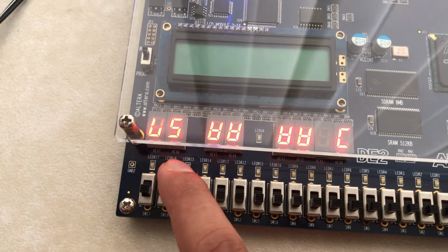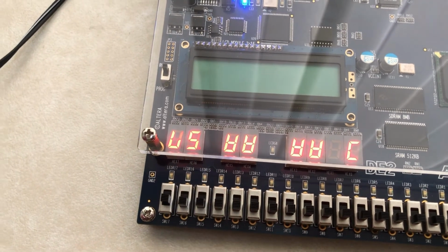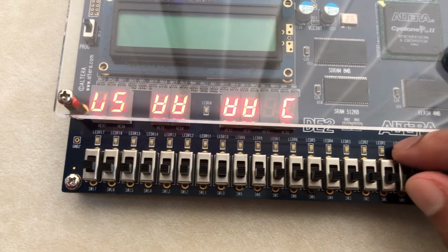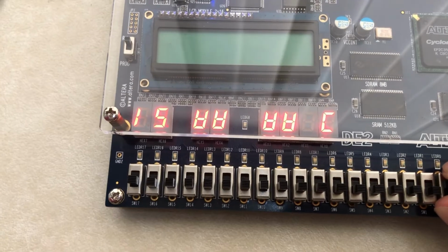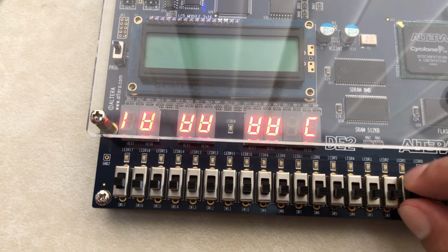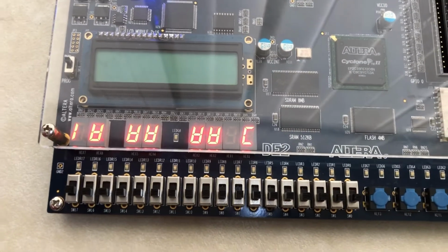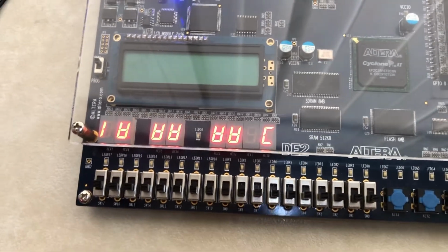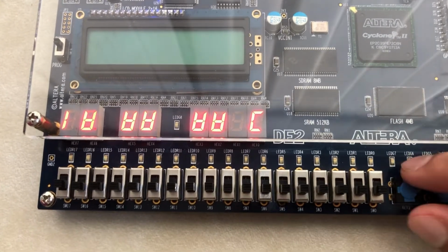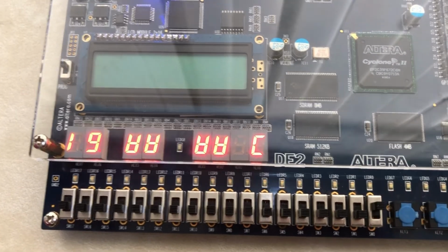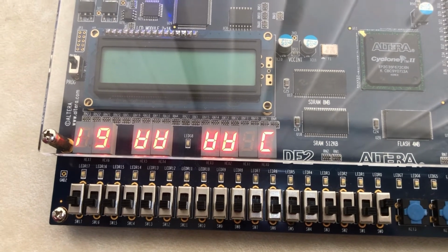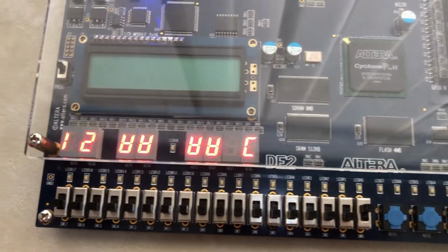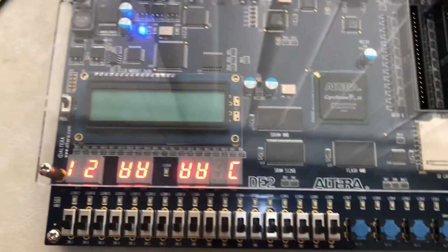Now if we push 10 cent, you can see that HEX 0 and HEX 7 and 6 both represent our countdown counter. If we push 10 cent, it starts moving. For the 20 cent it's the same, it's moving, but there is some problem with the function, because our waveform was accurate and we are getting every result. But when it comes to the FPGA board, there's some problem. When we push 10 cent, it's supposed to show us 10, but it keeps moving, like sometimes 11, 14, 18 and so on. Apart from that, other parts are working. Thank you.